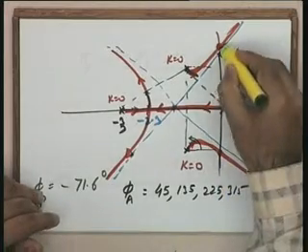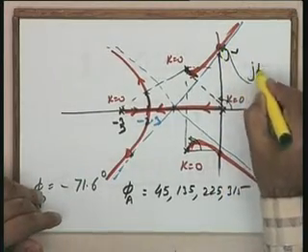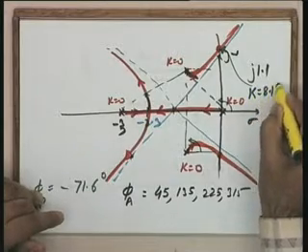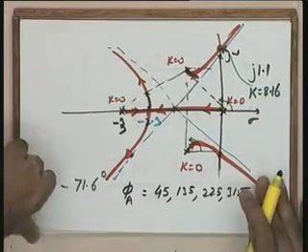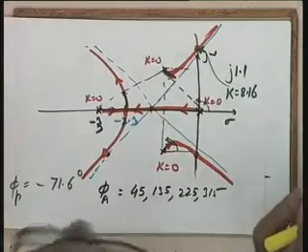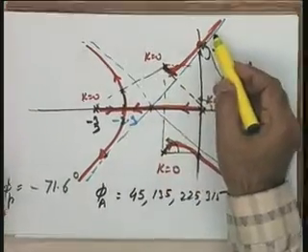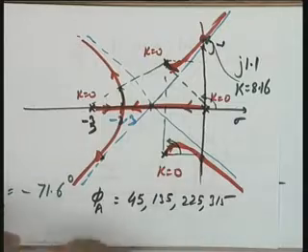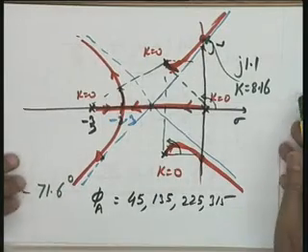Let me give you the result. I find that as far as this point is concerned, it is j 1.1 and corresponding K is 8.16. Coming from my notes, please. K is equal to 8.16, starting from K equal to 0, makes it oscillatory, and larger values of K will make the system unstable.